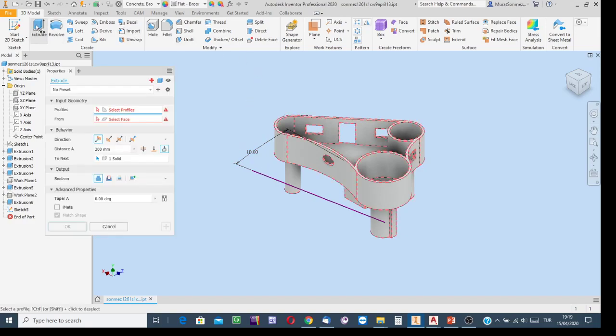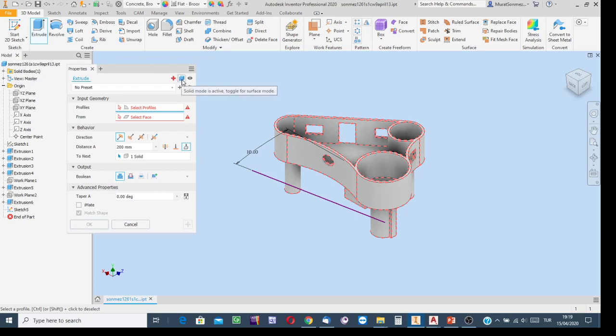Apply extrusion process. After drawing such a sketch in sketch mode, it corresponds to the edge of the work plane, and then apply extrusion process. But here there is a trick. In the dialog box, click on this button, because automatically when we start the extrusion process, Inventor will be ready to find a closed profile, closed region, to create the model of a right prismatic feature.